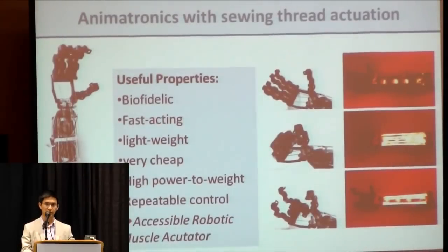We identified 3 models that dictated the dynamics of the new actuator, involving the thermal, electrical, and mechanical properties. With a variety of control techniques, we were able to achieve controlled rise times of 28 milliseconds. As a comparison, a human twitch cycle occurs at 100 milliseconds and reaches about steady state at 300 milliseconds, so we're far surpassing those performance levels. Furthermore, a peak power to weight ratio of 51 kilowatts per kilogram was achieved, whereas humans on average have a 0.32 kilowatt per kilogram power to weight ratio. So we're again 2 orders of magnitude above that, which puts us towards possible use for animatronic devices.